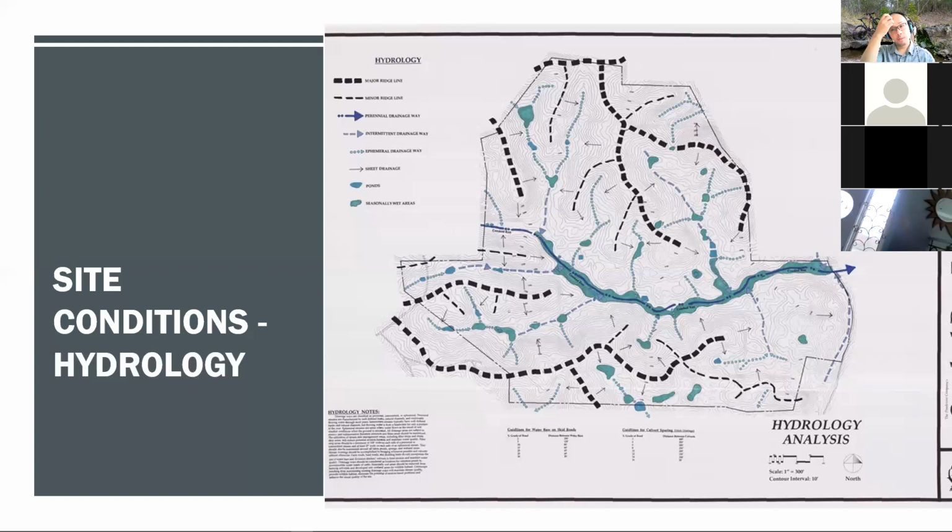So, with regards to water and water table hydrology in general, without on-site and off-site mitigation, urban development can have a significant impact on local and regional hydrology, because of course when you develop land, you will modify the land surface, you'll modify the slope topography and so on.